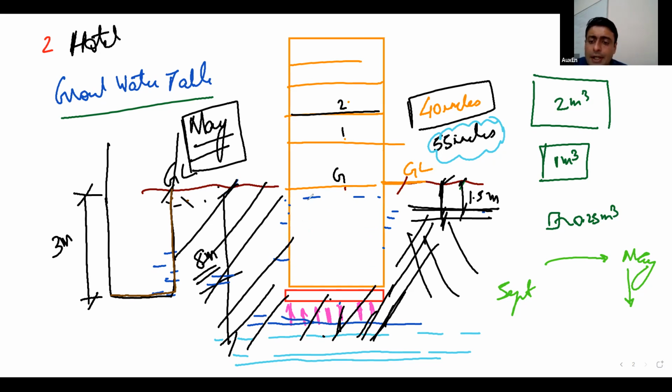Now afterwards, they had two choices. What were those two choices? That this raft should be replaced with a load bearing raft, which could take the uplift pressures, and you needed to redesign these walls also. So finally, the budget that would have been involved in these repairs was too large. They decided that this was too large a budget to incorporate.